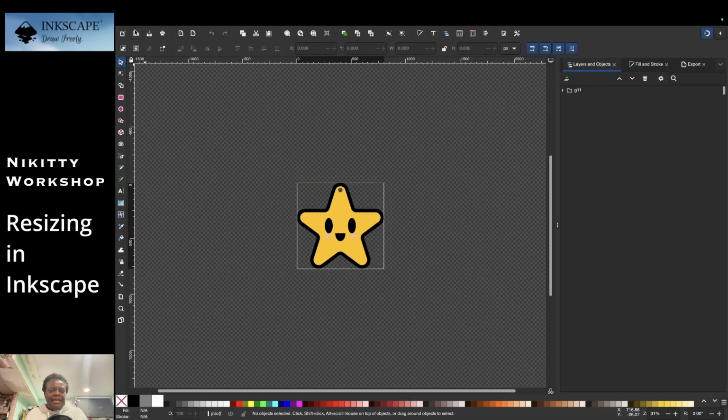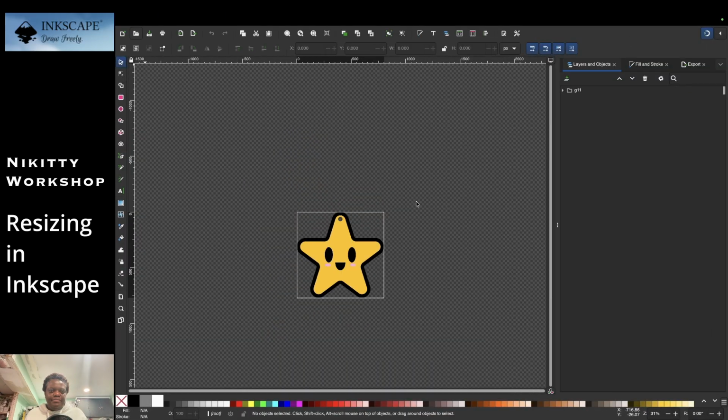So when you do that, we have Inkscape here. So this design, if you click all and look at the size, we're going to put it in inches for now. Remember when I designed it, it was 2 inches at its largest. When I export it as an SVG, it's coming out at 8. I think it depends on the pixel setting. I'm just guessing. It comes up bigger than what it needs to be.